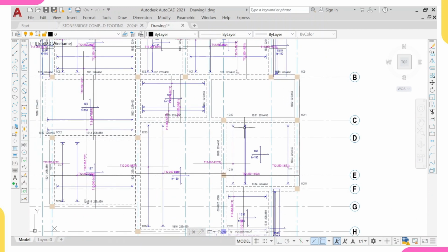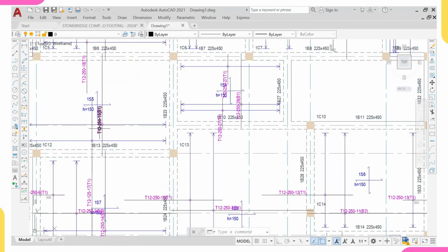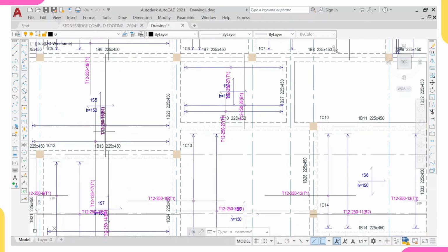The reason is that if you are in all these African countries where they tamper with quality, please make sure that once your slab design gives 250, you decrease your spacing to 200, because as for me I'm using Y12 at 250. If you go to the market and get Y12, that Y12 will no longer be Y12. It will be something like Y10 or even Y8 or 9. And also we use the yield strength of steel to be 460. If you go to the market, the yield strength you'll be seeing there will never be 460.